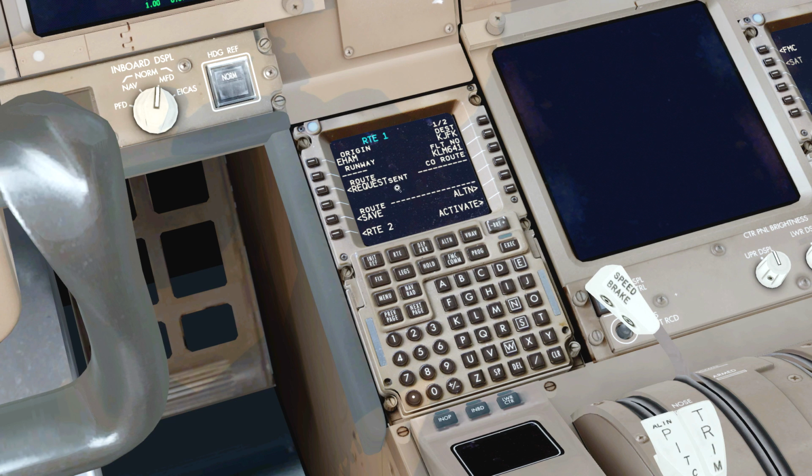It's now going to look in the database for which flight plan matches our origin and destination. And right now you have a message that the Route 1 uplink is ready. So yes, we want to have that loaded. If you don't want to load it, you can just click purge. But we want to load that flight plan in, so we're just going to click load. There we go. Route 1 uplink is now loading. Very nice. And there we go. So it should now be uploaded.